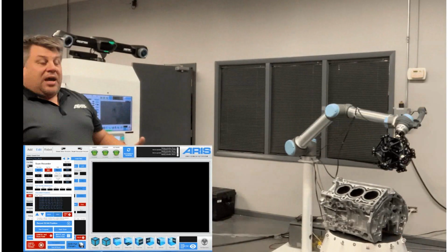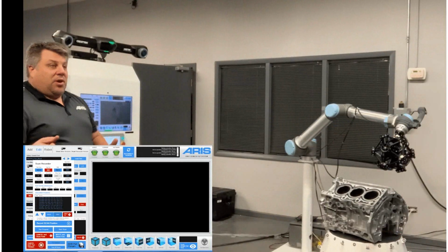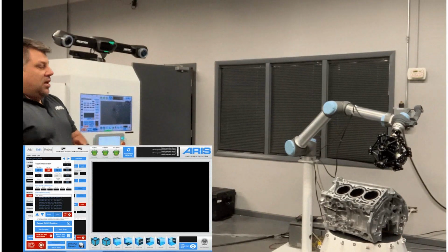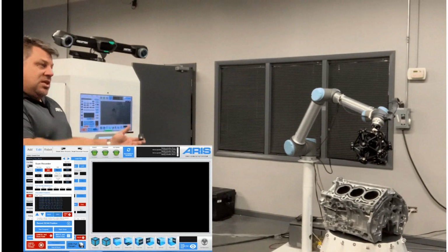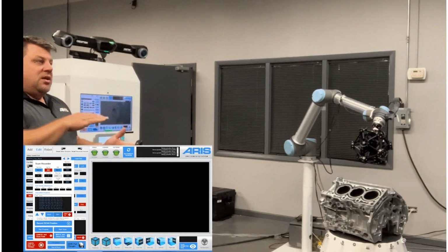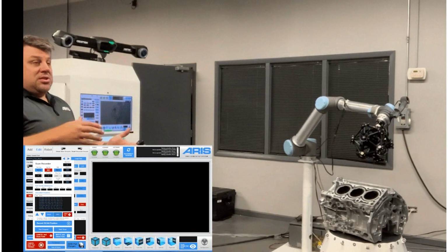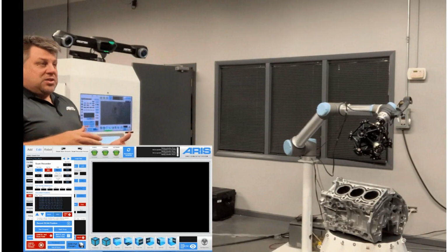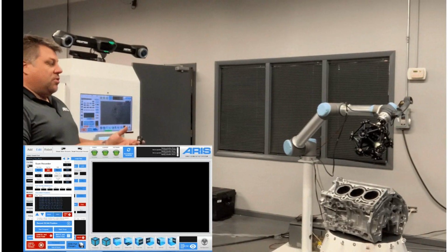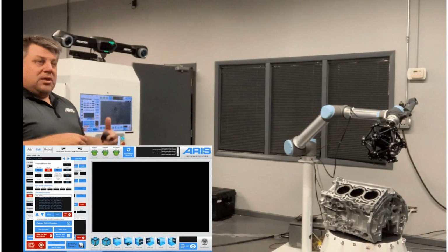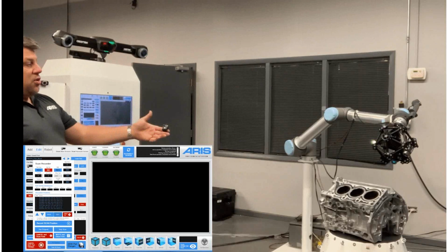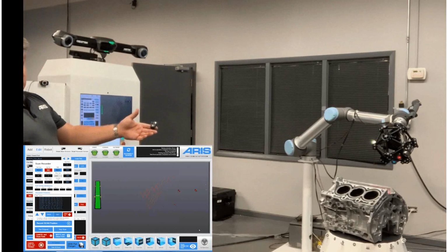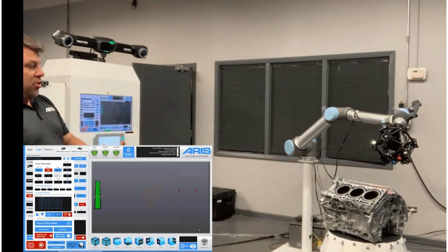So if we were looking for just information on dimensional accuracy of a die casting, I think this type of system is much more accurate, much more applicable to measuring die castings than a CT scanner. CT scanners are going to be much more adept at porosity and determination of internal quality on a 3D basis. So you can, in a 3D sense, tell where that porosity is at.